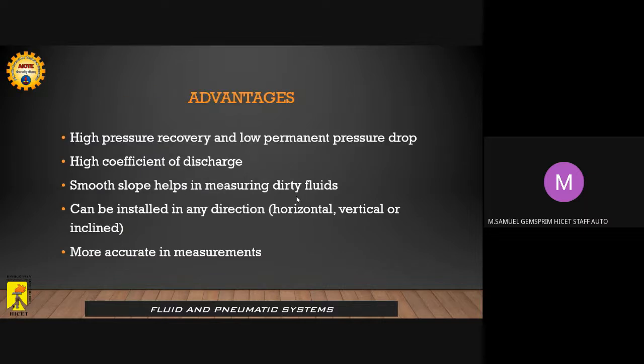Since we have this construction, we got many advantages. First of all, high pressure recovery is possible, since we have the diverging cone area, it is sufficient to bring it back to the original condition. Then high coefficient of discharge. So here the coefficient of discharge value is high, so no need to worry about the working operation parameters.